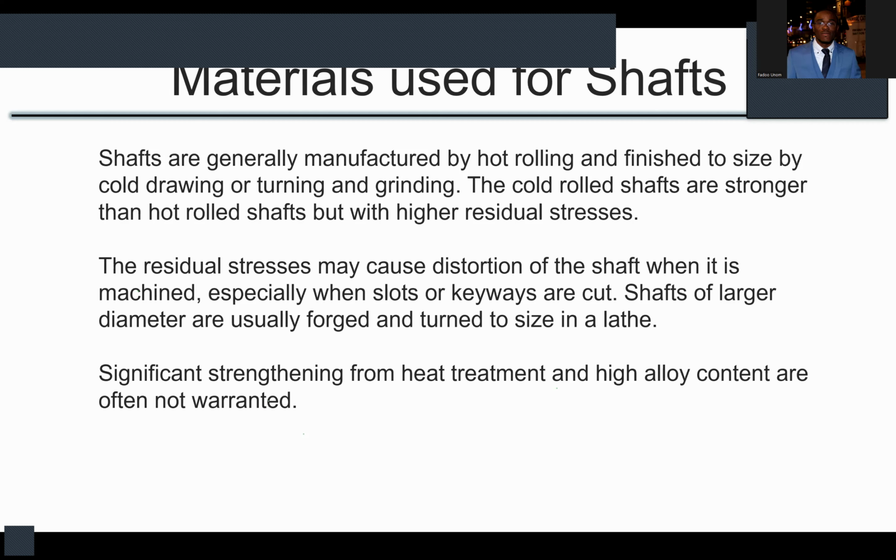that are not relieved when you stop drawing. So they still remain inside the shaft, and when you come to use the shaft, additional stresses will enhance easy failure. So we want to reduce residual stresses a lot. Fault lines and fractures usually begin at places where you have residual stresses. The shaft is working normally, and then it just fractures and breaks. Wow! What happened? Oh, it is because of residual stresses. There were already stresses inside from the manufacturing of the shaft.